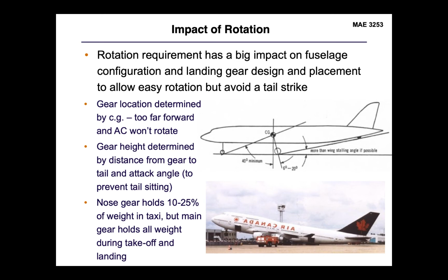Now, the rotation requirements really dictate the configuration of our landing gear. This is something that we haven't talked a lot about within class, but you can start to see that this is going to have a pretty big impact. We have to think about the requirements from the forces being applied to the aircraft as it's rolling down the runway. We want our aircraft to be stable, with the capability to rest on its wheels without tipping over while it's sitting on the runway or rolling down the runway. But once we have significant dynamic pressure acting on our control surfaces, we want the pilot to be able to activate the rotation phase of the aircraft, essentially by providing a little bit of negative lift in a traditional configuration, or positive lift if you have a canard on the nose of the aircraft, in order to generate a moment to pivot about the center of gravity.